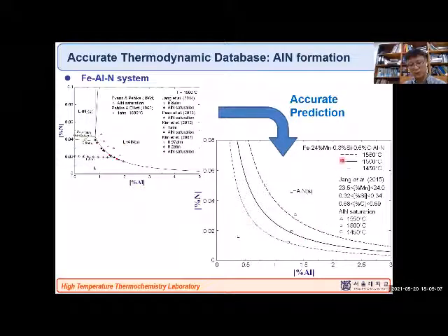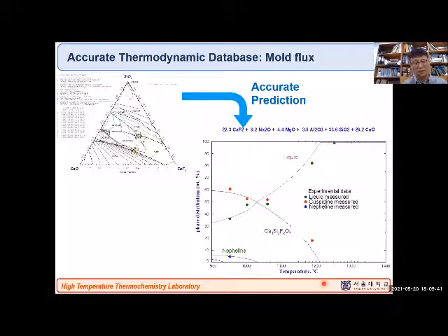Here, this is a very high alloy composition: iron, manganese 24%, silicon, carbon. And we want to know what the nitrogen content is, depending on the aluminum addition in this liquid metal at 3 different temperatures. Before we had these 3 data points, we did a prediction first. And then we got the data points from our colleague. And we say that, okay, our prediction was very, very accurate. So our thermodynamic database is now good enough for predicting in the new area. That's what I want to say.